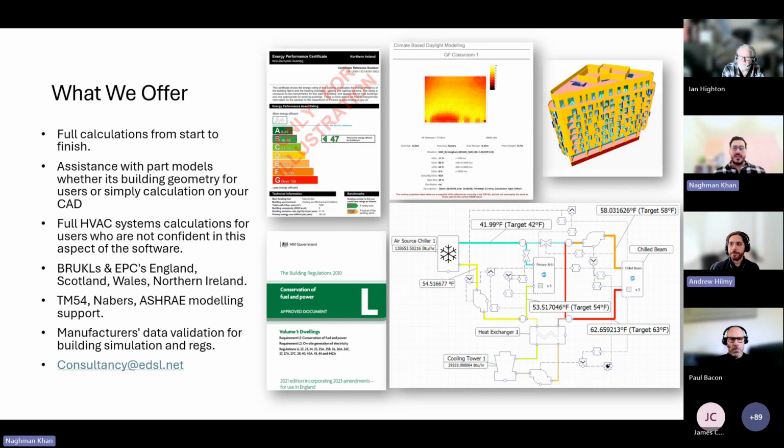Another question was, can we have air source heat pumps being able to connect to electrical collections? Yes. That's how it works. We'll elaborate on that, Gareth. Well, it's a follow-up. There's the air source heat pump, and it's got to get its energy from somewhere, and you assign it to a collection, an electrical collection, and then the electrical collection turns up in the plant room, and then the electrical collection has to be serviced by PV panels or wind turbines or grid supplied electricity.